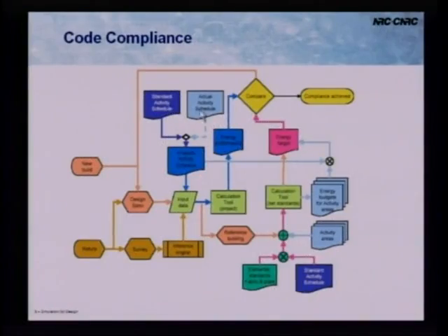The other thing, in terms of real building performance, and it's touched on here, is that for a lot of compliance checking and code work, activity schedules and various aspects of the building are predefined, and they may have very little resemblance to the real activity schedule or real use of the building. There are good reasons for that, but it means that in a lot of cases, the predicted performance from a code compliance type run is not similar to the real building performance.